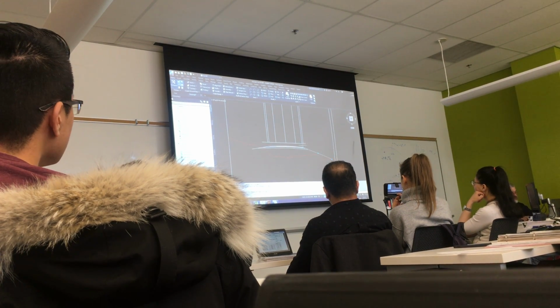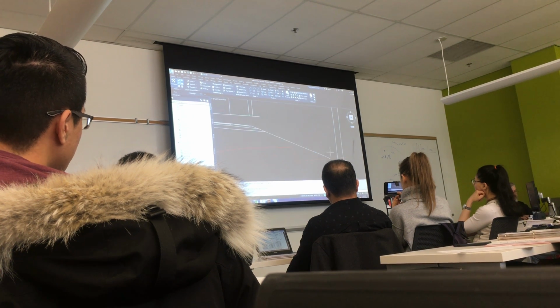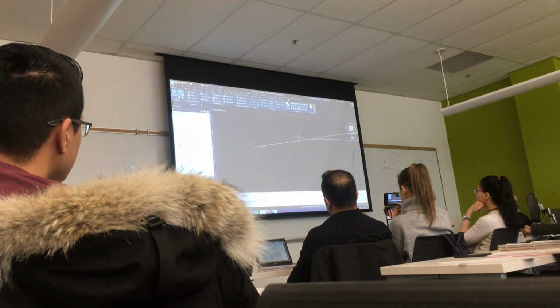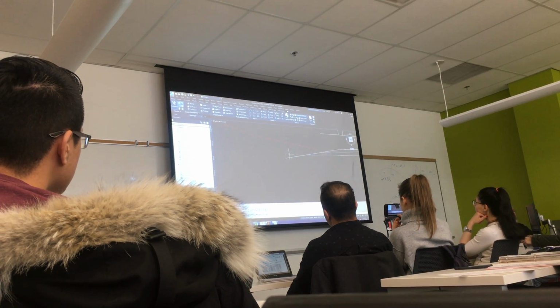This is a fill slope. Just extend it till you touch the ground, right? And then we're going to ignore the ditch beyond that. And we'll just tie it. On this side, you'll see this point is below the ground. This is going to be a cut.